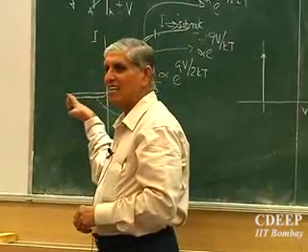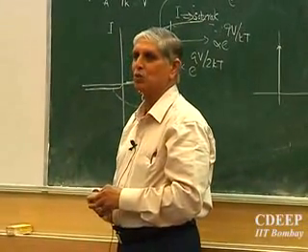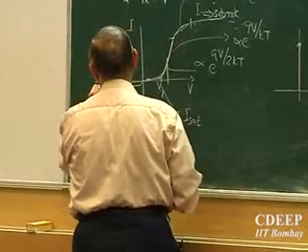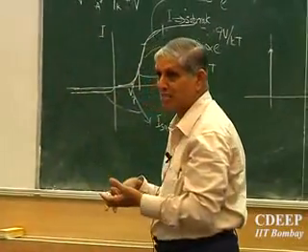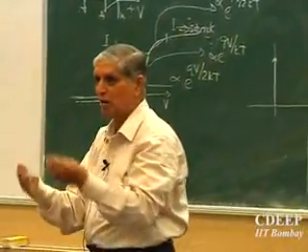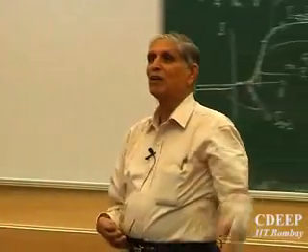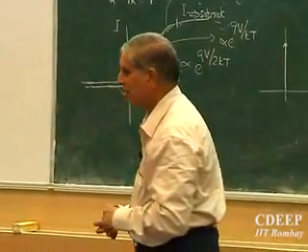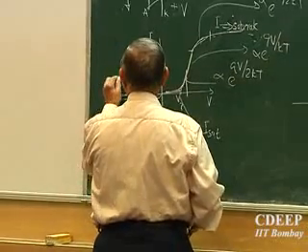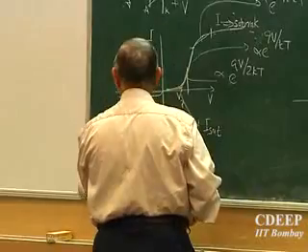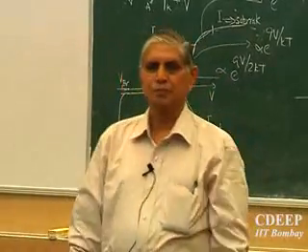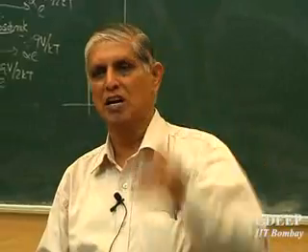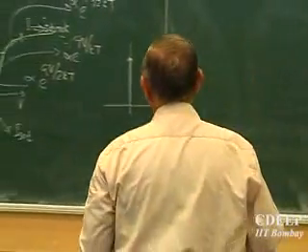So if I see larger reverse bias, I find that the current is very small, and it continues for a while, compared to this voltage maybe around 0.75 maximum, whereas this may be around 30 volt, 50 volt, 100 volt, 1000 volts. A power diode rectifier, as it is called, can stand up to 5000 volts. So it's not that it's only 1000 or something. Any number could be very large, depends on the design. And at this value, what we call breakdown, suddenly current starts shooting. So the device in reverse bias otherwise was having very low currents, but suddenly the currents start shooting, and it's called breakdown.